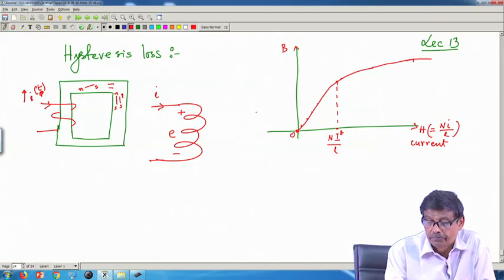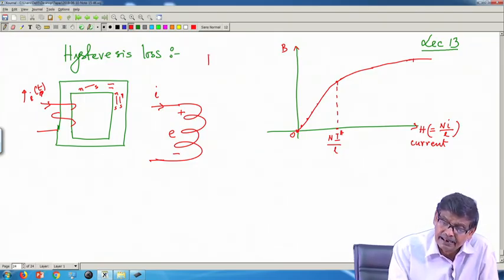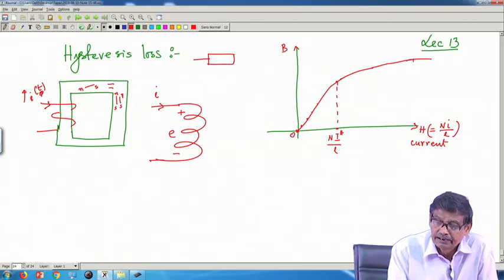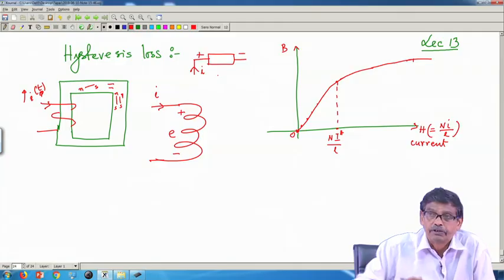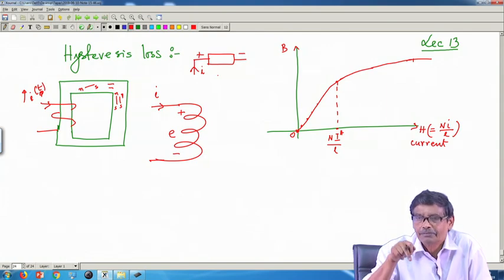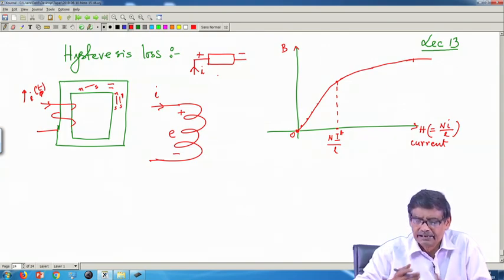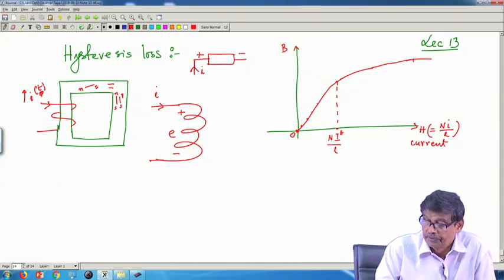That is why we got plus minus. Now, in any circuit, if an element has a voltage across it of this polarity, if current is entering through the positive terminal of that element, then we say it is absorbing energy, as in the case of charging a battery. To the plus terminal of the battery, you have to inject current, then only battery gets charged. So, energy will be absorbed,